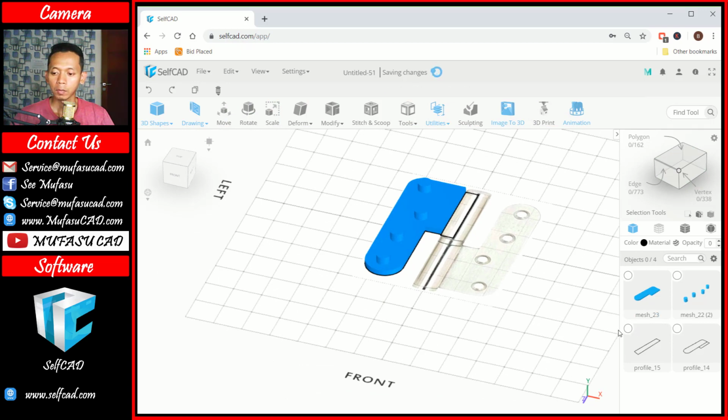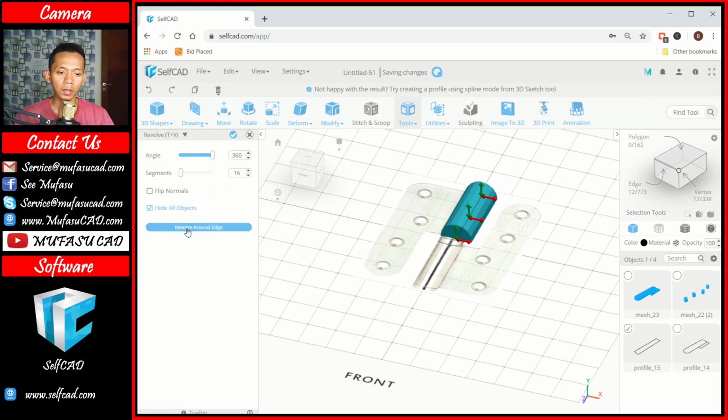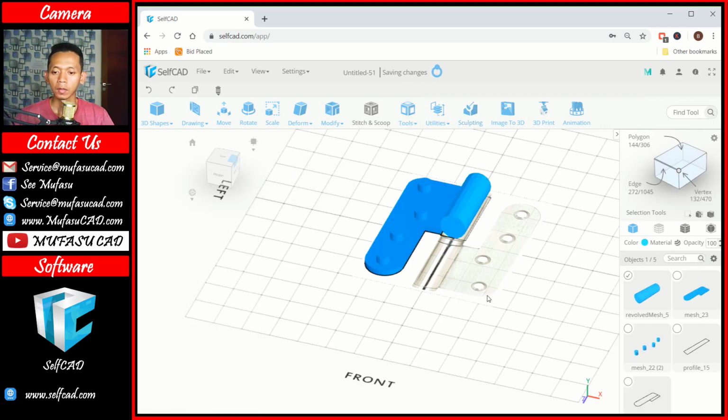In here I will create 3D models again from this profile. Okay, we can use a revolve command. We can revolve with revolve around edge. You can click at this edge and click OK to apply.